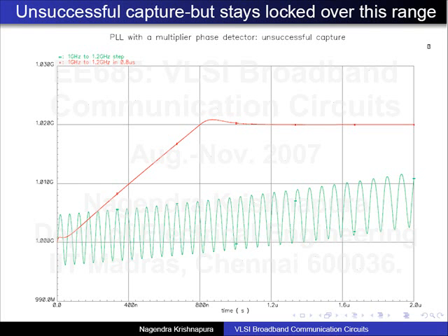No, because this is an ideal case. What happens is, whatever I described still happens, but much more slowly. Now, the control voltage is small amplitude. So in every cycle, the positive part is getting fatter and the negative part is getting thinner. Okay? But to a much lesser degree than before, because the amplitude itself is attenuated. So you can see that phenomenon here also. And clearly, in these parts, the waveform is kind of non-sinusoidal. This positive part is fatter than the negative. Okay? Now, with everything ideal, it may still capture, but it will take a very long time.